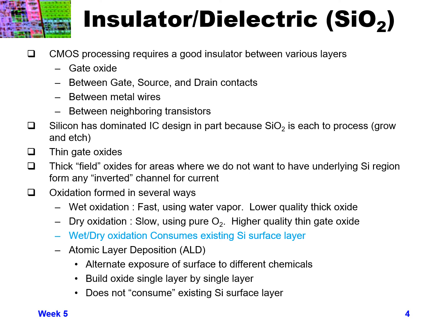The better insulator you have, the less capacitance you have. The more capacitance you have, the more it slows you down, and the more power you have to use in order to switch things. So reducing your capacitance is a huge deal. And then, of course, your insulator, dielectric, is used as your gate region. You need a dielectric for your metal oxide semiconductor, the oxide part.